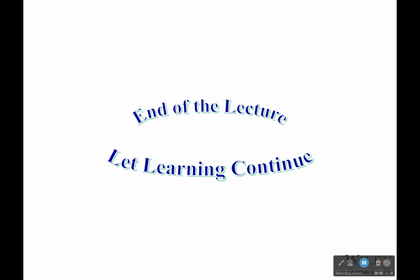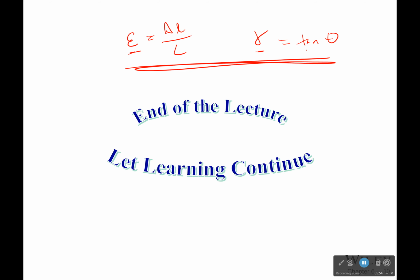Okay, so in this time we have introduced our strain and shear strain. Remember that they are unitless. So you will sometimes see shear strain referred to in radians, which is kind of a placeholder more than a unit. You'll sometimes see our regular strain termed as strains. Either way, don't worry about it. What are they? They're a change in a dimension over the original dimension. In this case, it's going to be tan of that angle. So it's how much the angle has moved from 90 degrees. How much has the angle changed from 90 degrees? This is important because it's how we look at deformation.